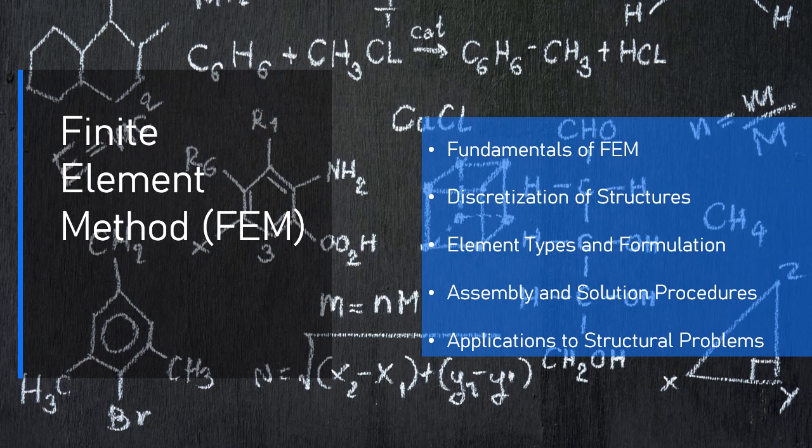4.2. Types of elements in FEM. The type of element chosen for discretization depends on the structure being analyzed. Different element types are available for different dimensions and structural applications. 1D elements, line elements, used for structures that primarily experience axial deformation, such as beams and bars. Common types: beam elements, truss elements. These elements are defined by their length, and the DOFs are usually displacements along the axis of the element.